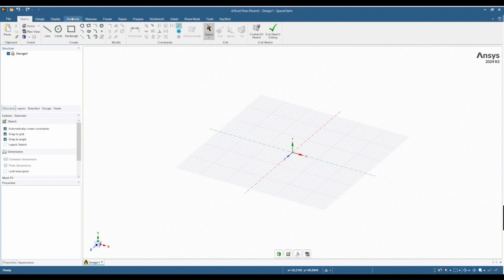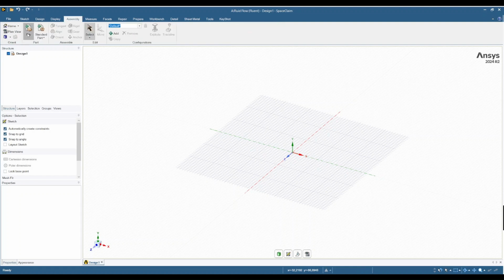Here we're going to go to assembly, then to file, and here we are going to go to the STL files that we created before in the geometry preprocessing tutorial. We're going to select the format as STL. As I said, take care of the units that appear here, the STL units. In our case, it's in millimeters, and we will load the initial mesh. In our case, we have called it ventricle 0. So we load this.